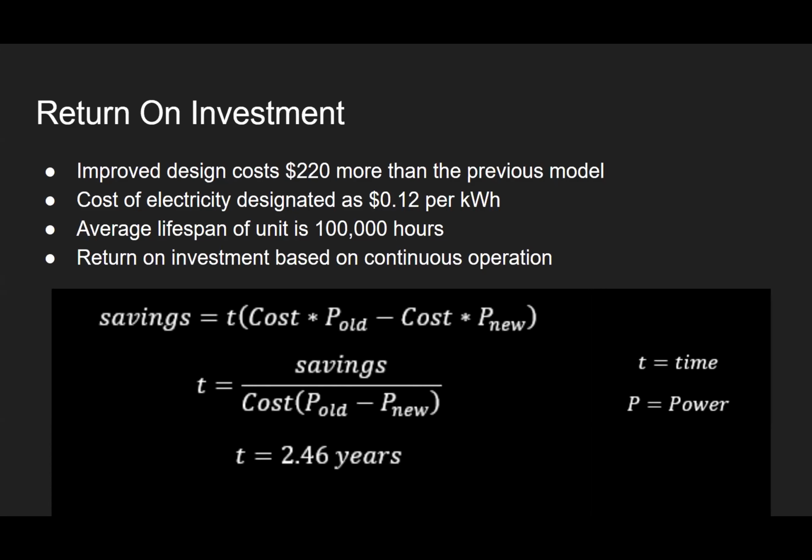Hey guys, this is Sam Wade with the Advisory Council. So you guys mentioned 90 feet per minute. I guess you're aiming for a non-linear or non-laminar flow. Which standard does that come from? Is that an HVAC standard, or do you know? That was just the clean room standard. Most clean room operations, that was provided to us by Gordon. That was the target that they wanted us to achieve, that most clean rooms are operating at. Okay. Is there any opportunity, I guess you're aiming for that 90 feet per minute flow?